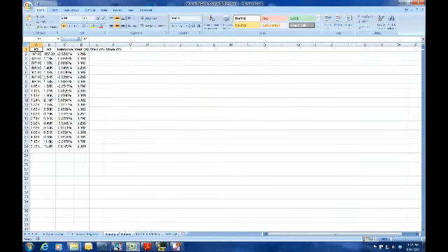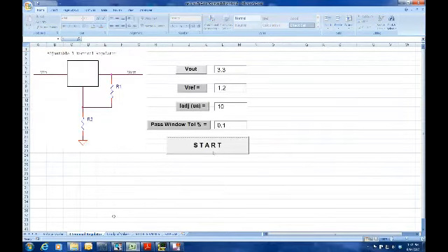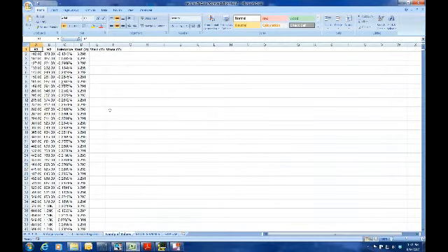And it looks like since we want to use rather small values for R1, the 107, 187 probably will be our best case, unless we want to be out of regulation a little bit. So let's put in 0.03 and see what happens. And here we now have more values, and we can see the tolerancing on the output. So we can choose any of these combinations for R1 and R2 that satisfies what we're looking for. And here's the output voltage and the tolerancing.